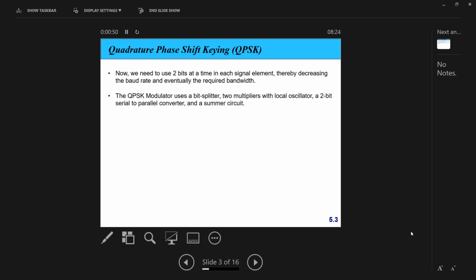And we send one bit per signal. Now I need to increase the R. Instead of sending one bit, 0 or 1, I need to send two bits: 00, 01, 10, 11. So I need to send any two bits at the same time. Okay. So how many levels now? L equals 4.